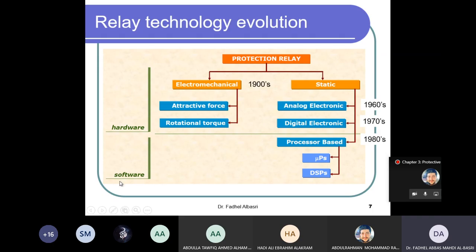So in numerical relays, in addition to the hardware, we also have software with which I can build the protection functions, the distance relay or the overcurrent function, using programs. That software will determine the magnitude of the currents coming from the CT. It determines its phase shift. It can determine the harmonics within that current. I can compare that current with the settings. I can create a delay. So many things I can do, but all of that is software.